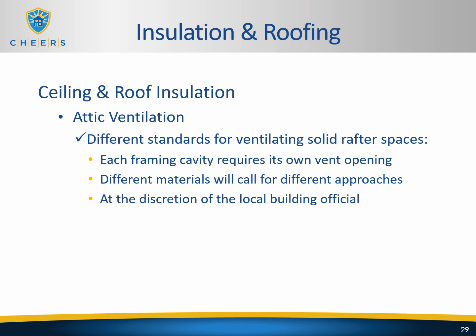So there are different standards for ventilating solid rafter spaces. Everything that we talked about as far as attic ventilation is concerned, we're talking about a regular attic. Now, a solid rafter space is an example of a cathedral ceiling or somewhere along those lines. So each framing cavity for a solid rafter space requires its own vent opening. There are different materials that will call for different approaches, and it's also at the discretion of the local building official. So there might be specific requirements depending on the climate zone, on the jurisdiction that the home is being built in. But keep in mind the solid rafter spaces are a separate application than the regular attic that we just talked about.